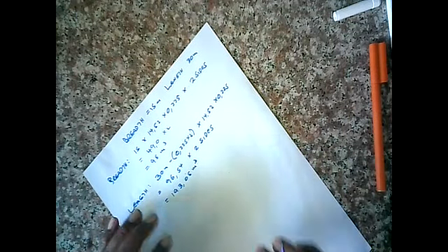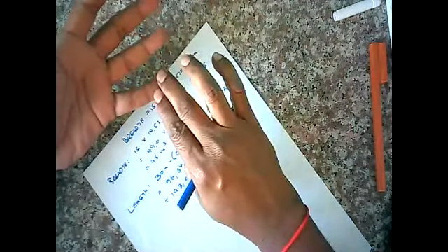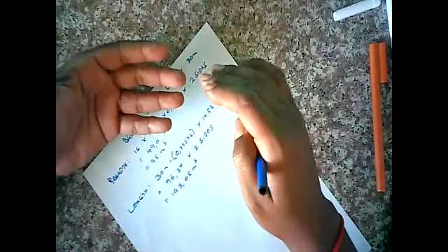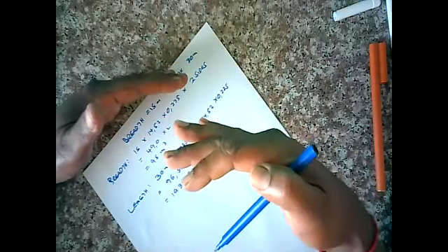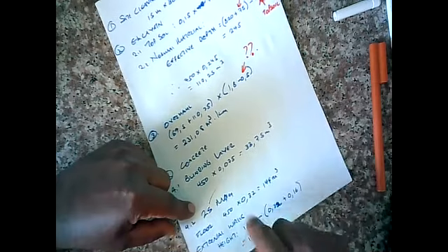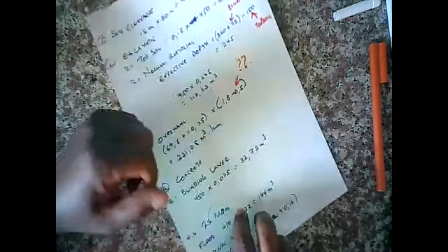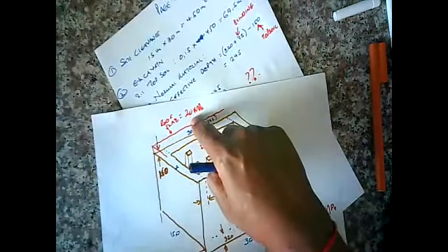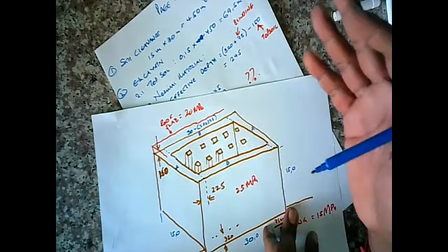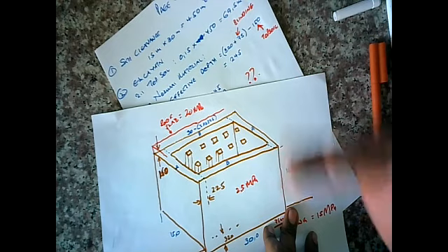Now, don't think we're going to go 15, 20, 25, 30 in numerical order. No, no, no. We're going in order of construction method or construction process. Because look at this. This is on the floor, so it's the lowest, 15 MPa. But then you've got 25 MPa around the walls. But when we come to the roof, it's 20 MPa. Now, if you had to do 20 MPa, it's like you're putting the roof on first before putting on the walls. That's not on.